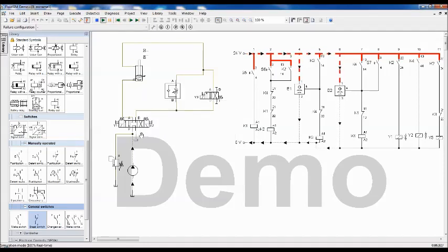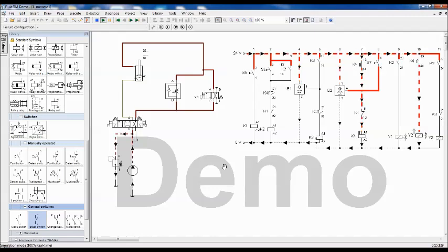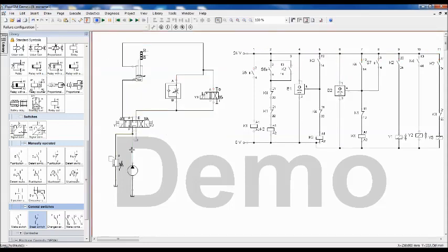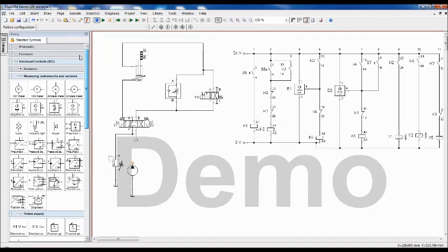Okay, let us see that when you operate S6, it goes with high speed, but there is no detection of the sensor. There is a problem. So what I'll do is reduce this cylinder speed by default. Actually, the throttle valve is not in the circuit.